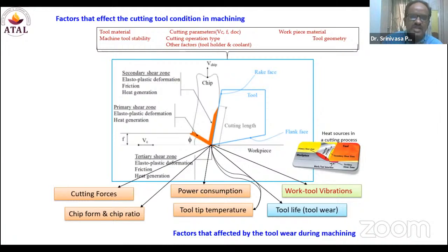To measure this in the direct method, you need to switch off the machine and take out the cutting tool. It can be single point or multi-point. Then only are you allowed to inspect the tool wear. Power consumption is also an output process variable. It will vary with the amount of forces and the input parameters. The hardness of the workpiece, encountered during the cutting and material removal, is going to affect the power consumption level.